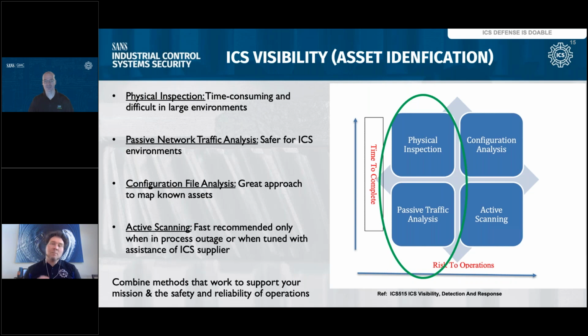Configuration file analysis is up on the top right. There's some risk to that. You have to touch a lot of different devices to get configuration file analysis. So yes, it is logging into devices, getting ARP table output, getting all of that information and piecing it together. So there's time consumption for that as well, but you may miss things. For example, you hit a firewall, maybe you're not down deep enough in the ICS to get information about assets communicating below there, your east-west traffic versus your north-south traffic as an example. And then of course you have active scanning, which is really not as safe an approach as passive scanning.